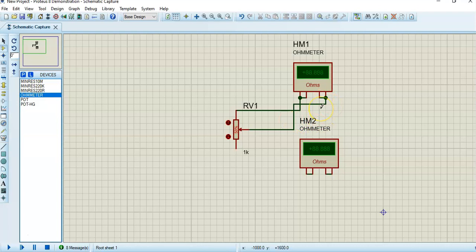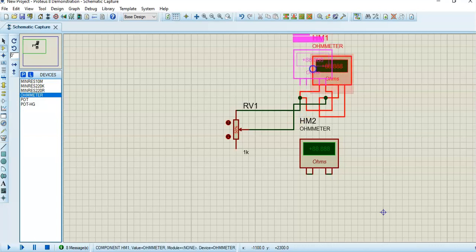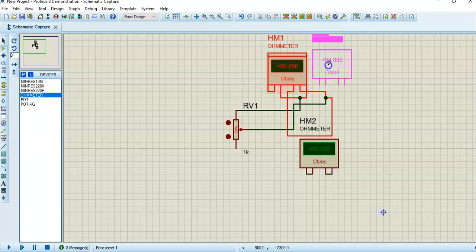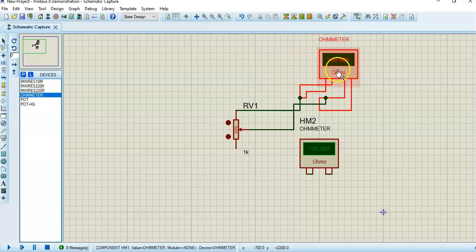Now if you noticed here, this is the auto routing. It has taken a path, what you see here, but you have to keep in mind these wires are not shorted. Only when you see this dot, like a junction, that's where the connection is made, not here. So you can try to move this further up or down. Oh, this is still worse now.